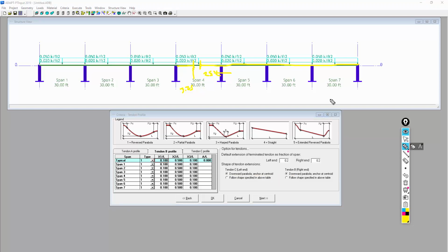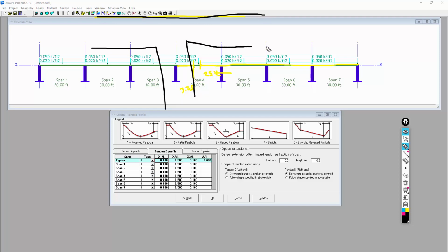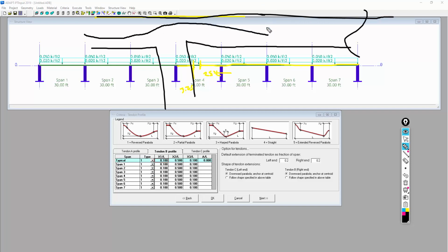So when this tendon, I'm going to blow this up a little. Let me use a different color here. I'll use the black color. And so we have a column here, and I'm going to just cut that off, and the tendon's kind of draping through here, and then it just comes here and it stops. So the question is, and this could be a live end at the pour strip face. This is like the pour strip here and over here, and we have another tendon here. So at this location, do we want this to be anchored at the CG? So this depth, this is 0.5 H and 0.5 H. This is rectangular, so we're just saying half and half.